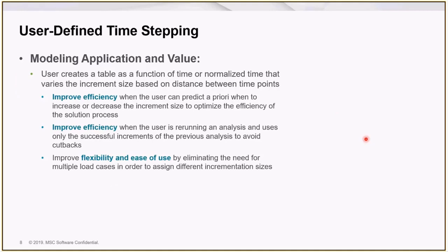But really, in describing it, the way to think about it is we have fixed incrementation, which is you define one increment size based on cutting up the time into even chunks. So every increment is the same size. And then you have adaptive, where you give it an initial increment size, a few other parameters, and you kind of let the program decide.